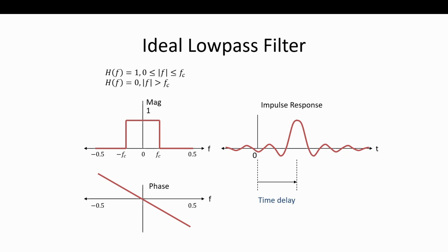Is the steepness of that phase graph proportional to the delay? It will be, because the steepness of that phase graph is directly proportional to how long we delay. And you're going to see how the number of taps will relate to this. The duration of the delay is proportional to the slope of it. That's right. So how far we push in that time delay is how steep that got. If we push even further, it's got to be steeper. So that's a good thing.